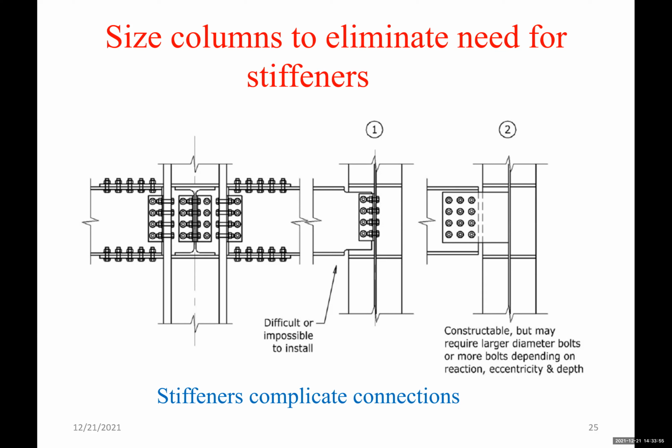And of course, once we provide coping, then there are more limit states that we need to check at the end of the beam. And as you can see also on number 2, if we are not doing any coping, then we are using an extended plate. Okay, and look how many bolts we are using in the extended plate. So we're using 3.